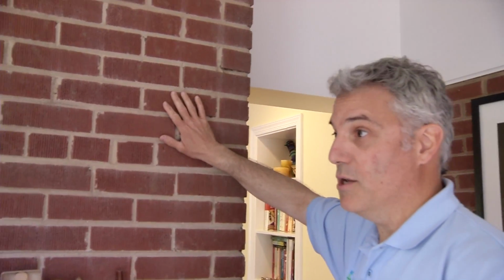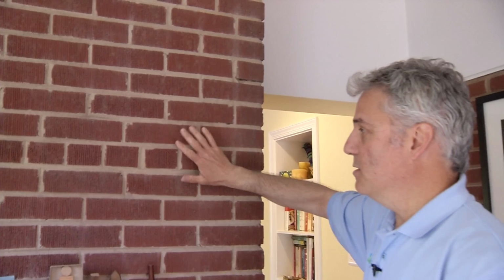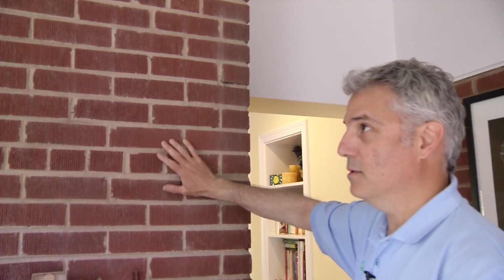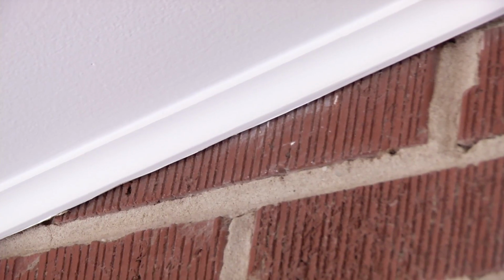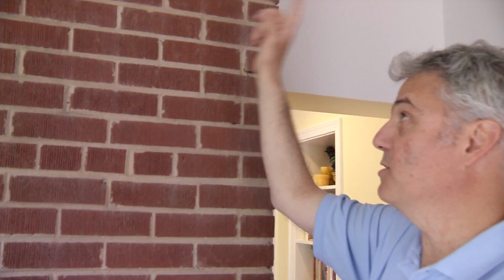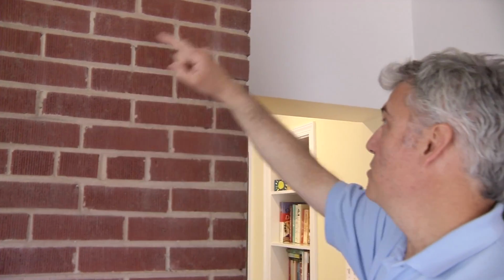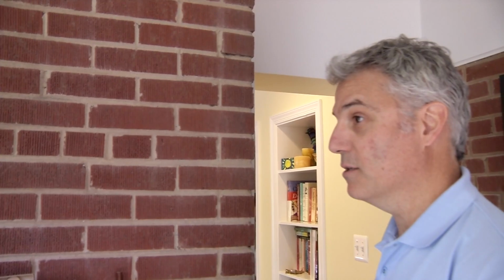You put an addition on your house, right? Yes. So this was an exterior wall of the house, and then everything this way is new construction. So when this was built here, it wasn't made airtight. There's easy ways to fix that, simply by caulking this area here and filling all this in, but it can make a real difference in terms of the amount of air leakage that you're experiencing here.